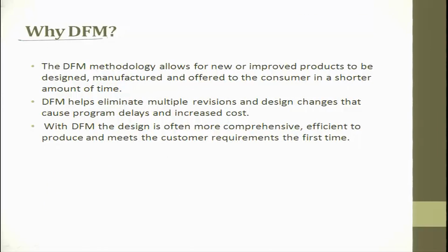Then why DFM? DFM methodology allows for new or improved products to be designed, manufactured and offered to the consumer in a short amount of time. So, the time from the design state to go to the customer state is very important. When you follow DFM, you will try to reduce that time. DFM helps in eliminating multiple revisions and design changes that can cause program delays and increased cost.